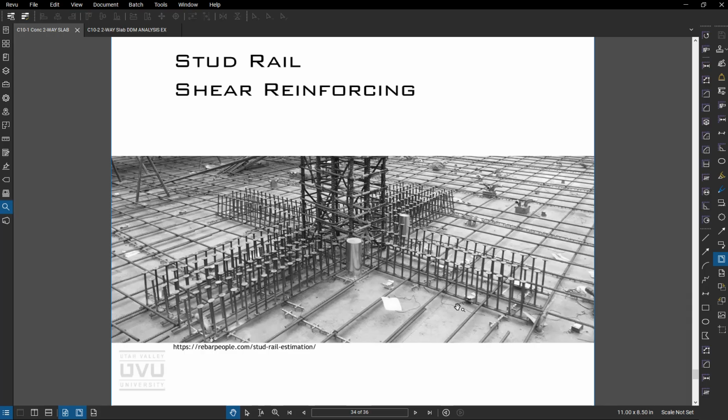And then the tendons you can see running through here. Where are those guys? Actually, I think I speak with forked tongue because I don't see any tendons in there. So it looks like this is just a mildly reinforced slab, or it's a post-tension slab that the tendons haven't been placed yet. Anyway, there you have that.